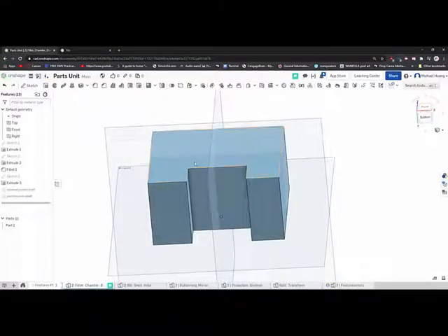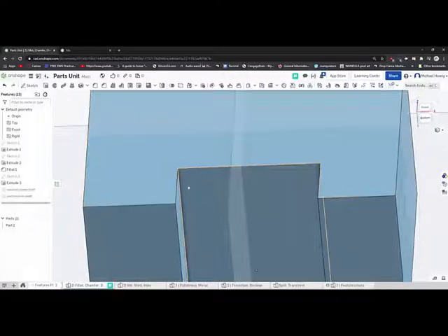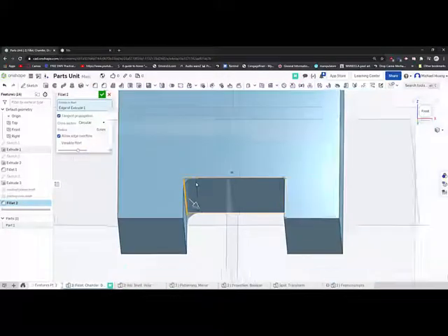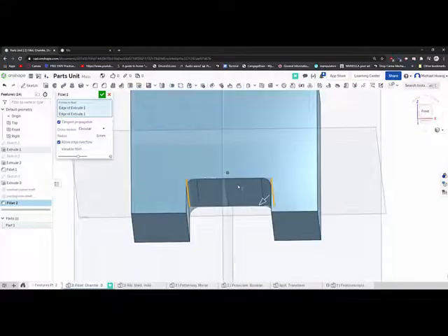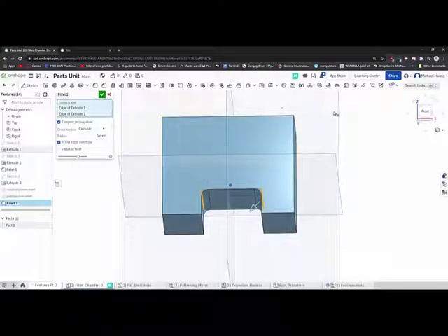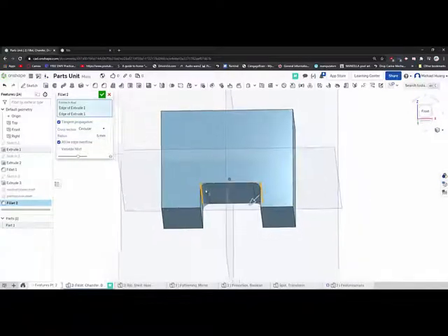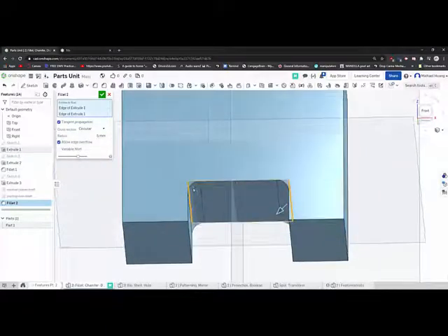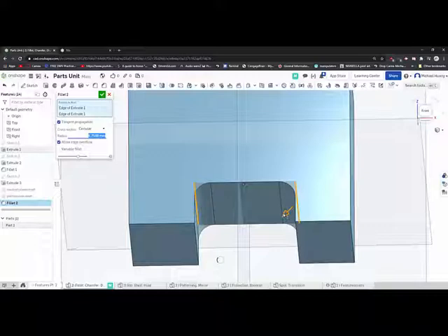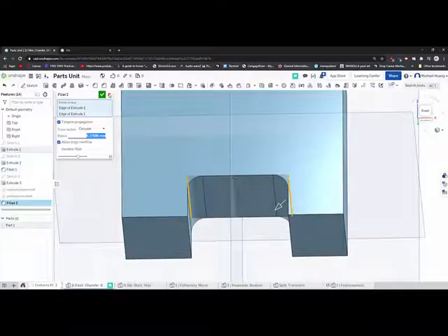And as you can see over on this edge, if a cylinder went past this, right, it's not going to create this perfectly sharp edge. It's going to create a sort of more filleted shape. So what you can do is you can fillet this, and when you transport this model into your CNC machine and it reads the data for it to be cut, it's not going to give you an error, right? So that's just one application, being able to avoid errors in your CNC and account for your bit's shape. Okay.